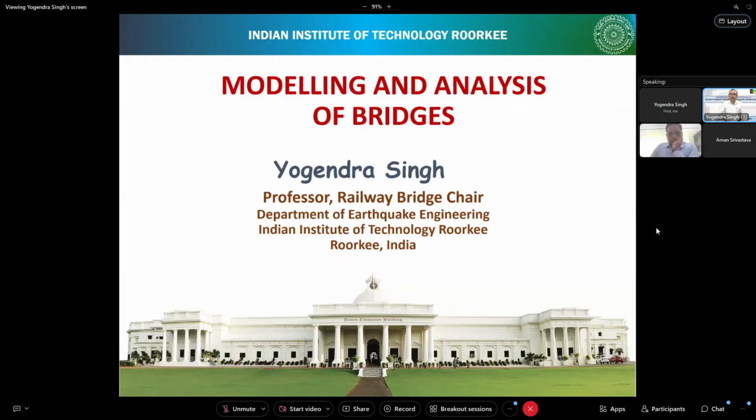In case of earthquake, there is additional complexity in the behavior of the structure because we design our structures to yield during earthquake. We never design our structures to remain elastic during earthquake. So our structure is subjected to non-linear dynamic behavior, which makes that behavior a little more complex. But in our conventional design, we don't really perform nonlinear dynamic analysis. We perform linear dynamic analysis only, and the effect of nonlinearity we take into account indirectly through the response reduction factor. That is the second type of action which we are going to cover.